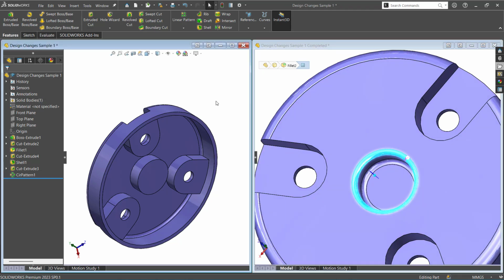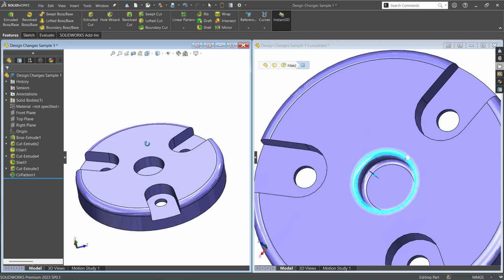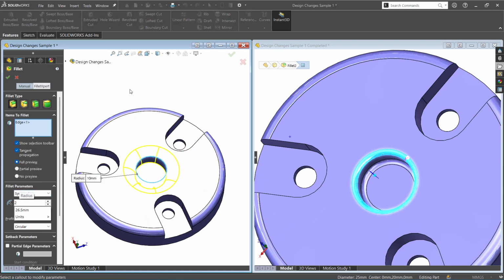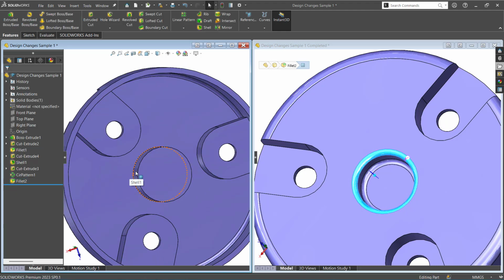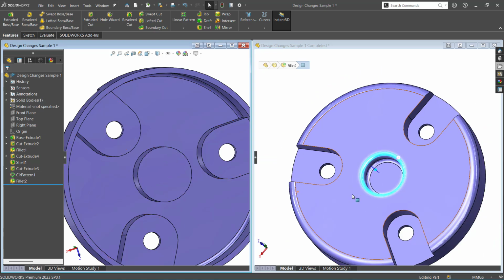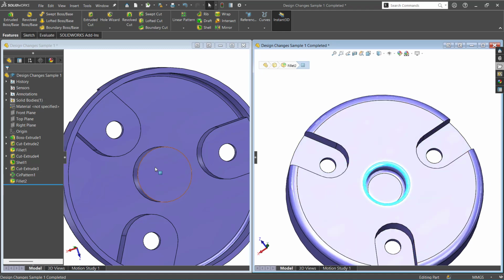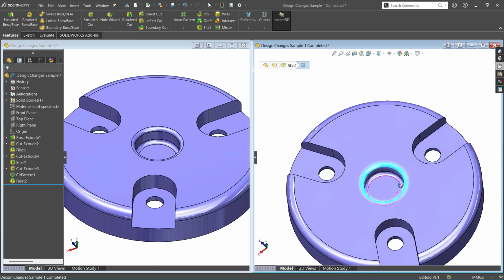Yeah. So now if I create a fillet here, will it work? Yeah. It will work. 2 and 2. Now you could see this side it won't. So his requirement is on the top. This is fine for him to create later, but this one should be before, meaning before creating the shell I should create it.